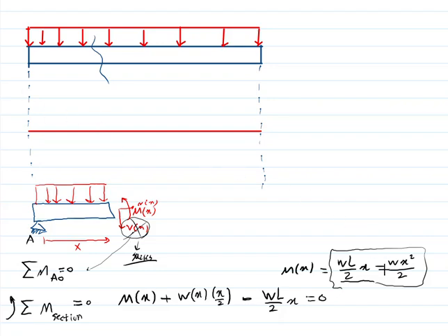First of all, it says when you start your parabola, it has a positive slope. So it must be like this. Second thing is the curve direction. You are negative here, so you know the hands are downward. So it says we have a maximum moment somewhere.